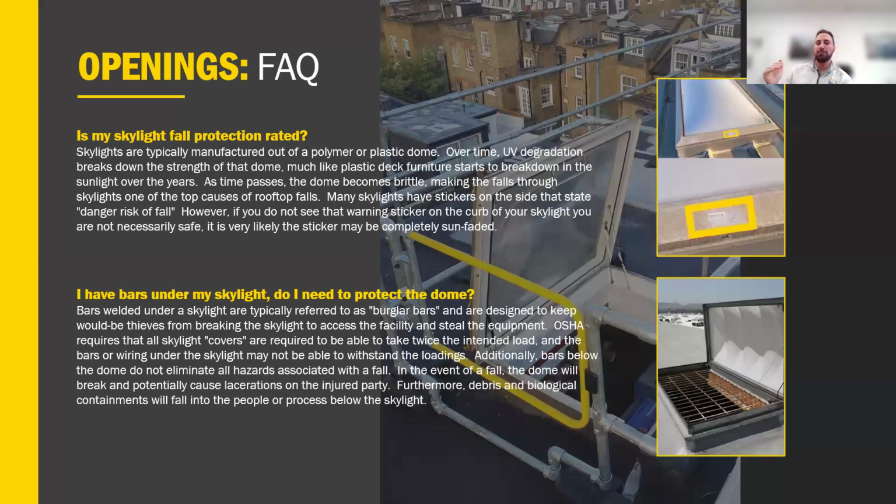The reason they're not for fall protection is because they don't eliminate all the hazards. They don't eliminate me crashing through the dome. They don't eliminate the lacerations, biological contaminants, or the struck-by hazard down below. So we have all those other hazards that we need to contend with, and they're probably not weight rated to 2 times intended load, which is what the OSHA requirement is for fall protection, according to OSHA 1910.29, which tells us what the testing requirement is.